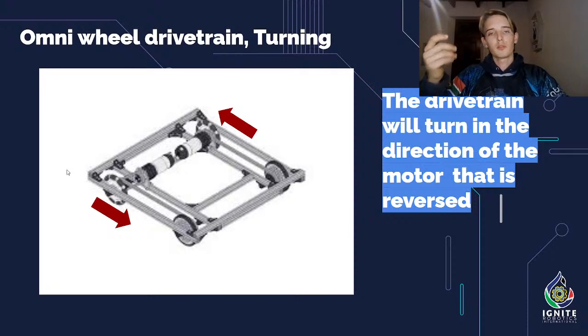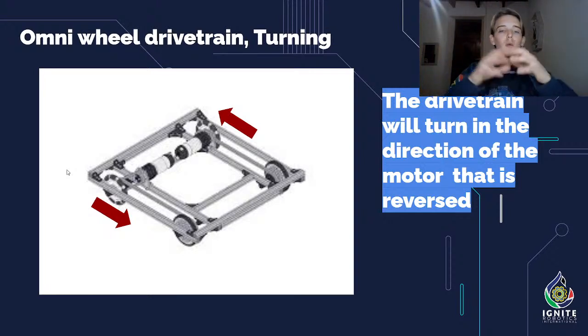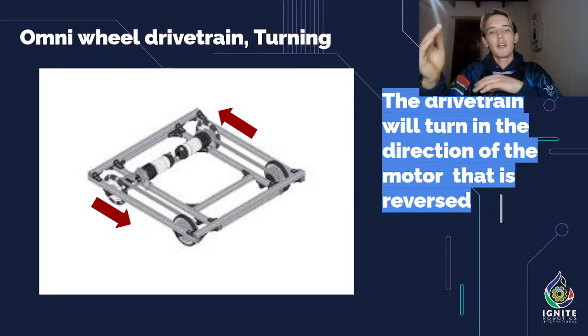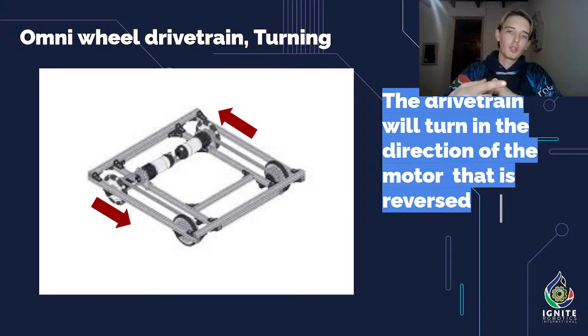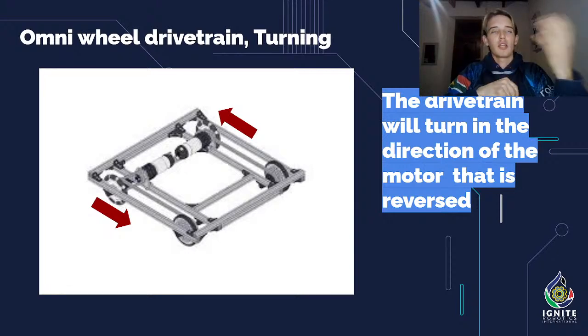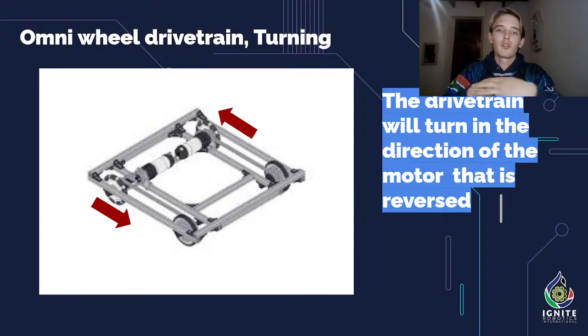Now this will cause problems because when you set a motor to power 1, it's going to go full speed forwards, clockwise by default, and if you set the power to -1, it's going to go in reverse. But if we want to drive the robot forward and assume both motors need to go to 1, because forward is positive, one motor is going to go forwards and the other is going to go back, because that's their default direction.